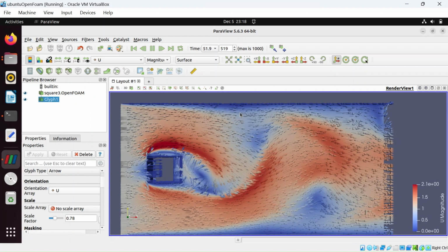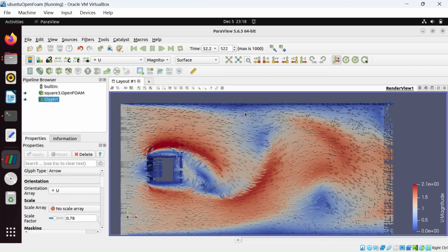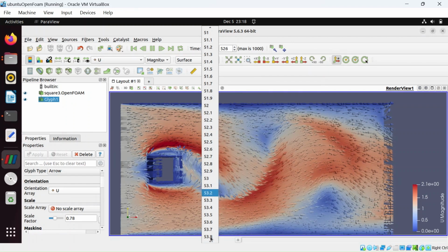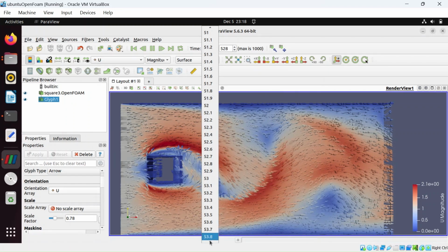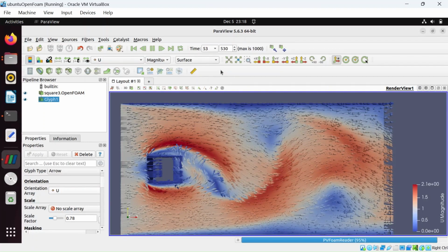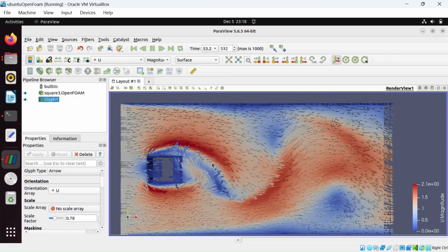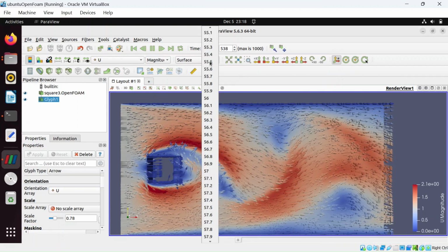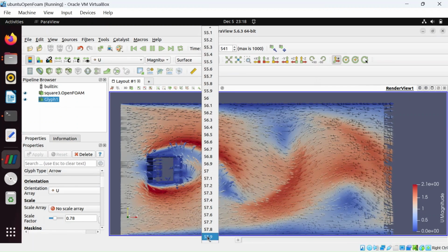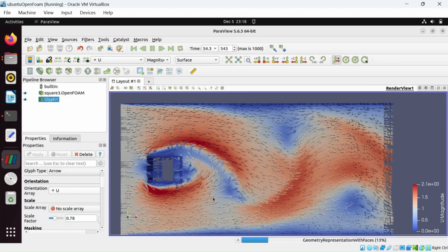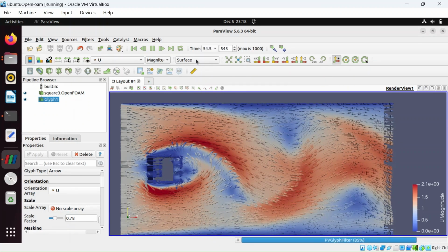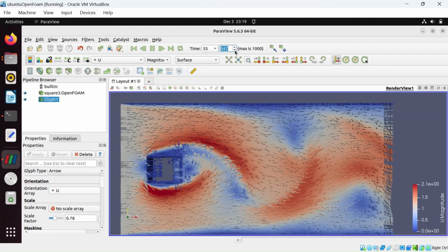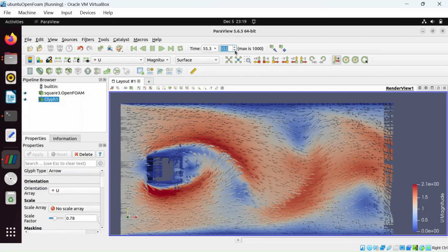Now if the Reynolds number is high, we can observe flow separation from the cavity wall, where the streamlines detach from the walls, and subsequently these streamlines may reattach as the flow moves around the cavity. For the velocity vectors, we can see the separation and reattachment points with a high gradient in velocity near these regions.